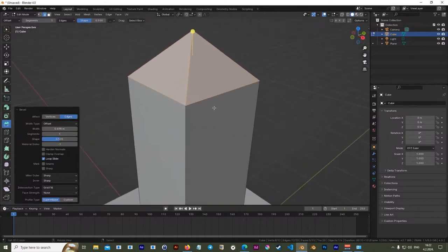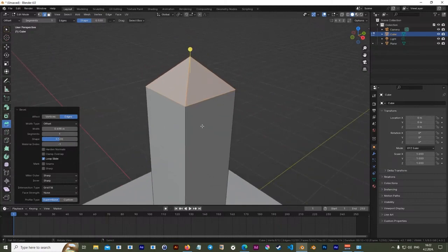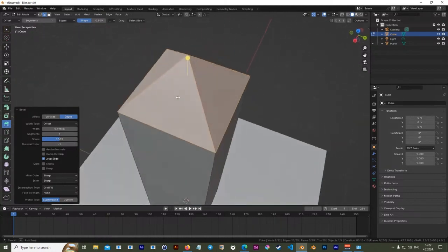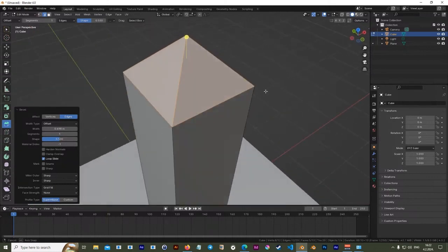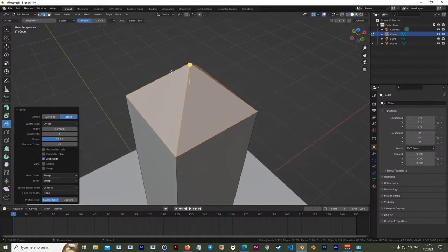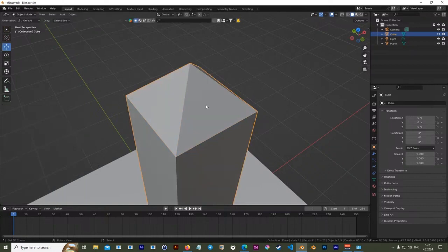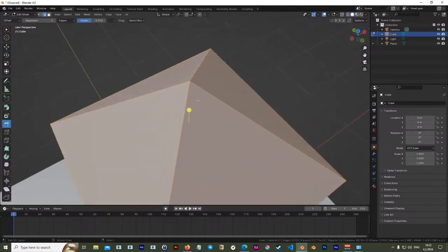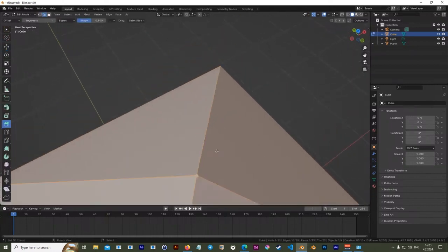People often create some complex geometry they want to bevel, but they can't do a bevel more than Blender can do. Blender offers clamp overlap. If you continue, you will have overlap. That's not good geometry, that's something wrong. So that's that thing about bevel.